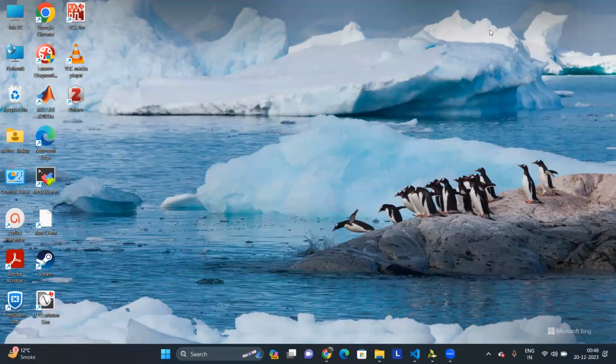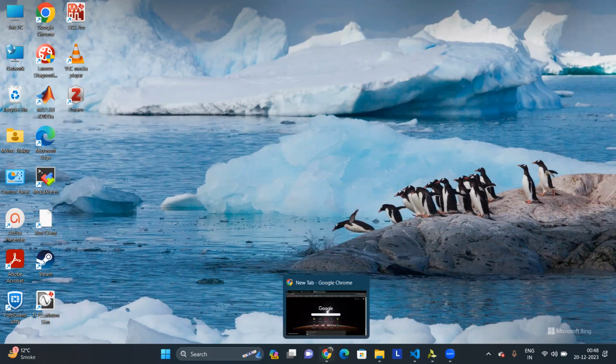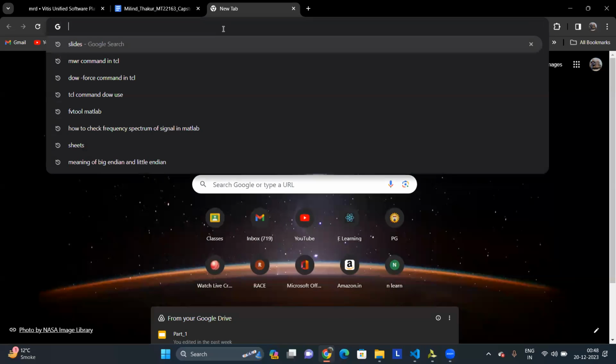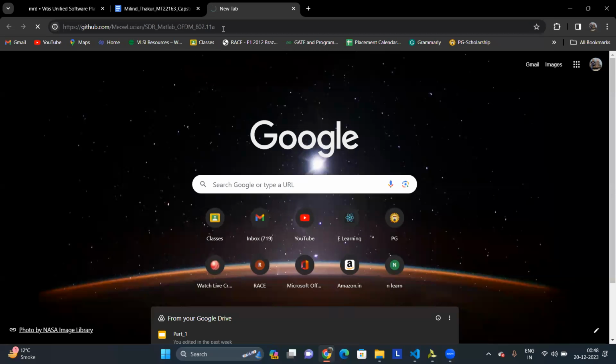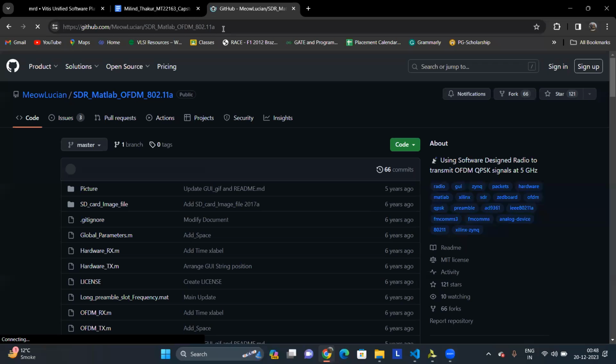Hi, in the upcoming set of videos, I will demonstrate how to implement OFDM using antennas on RFSoC. The first step is to download the base code. The base code that we'll be using is on the Meow Lucian GitHub profile. He has implemented OFDM 802.11a on SDR. Firstly, we will download the code and extract it.